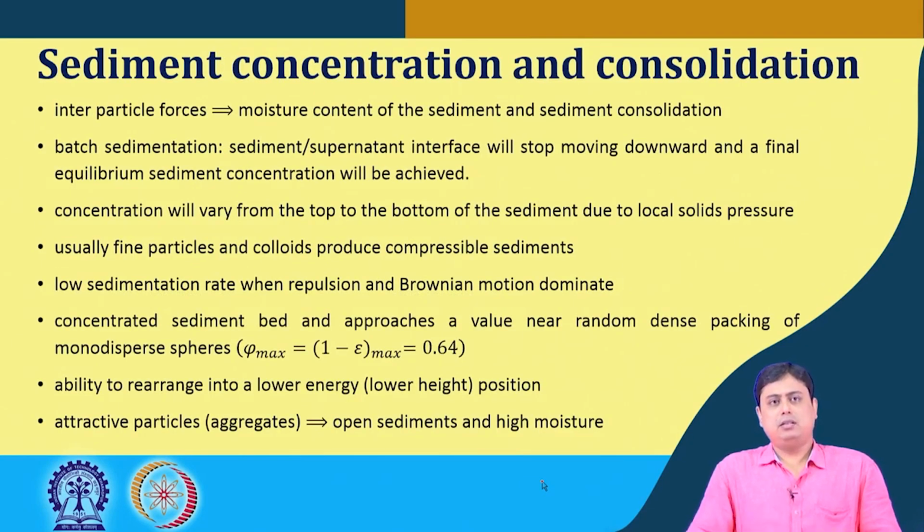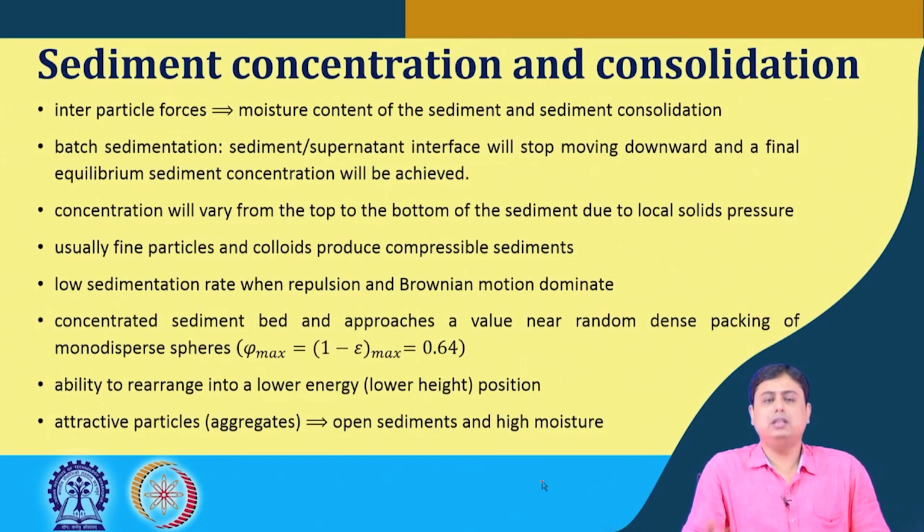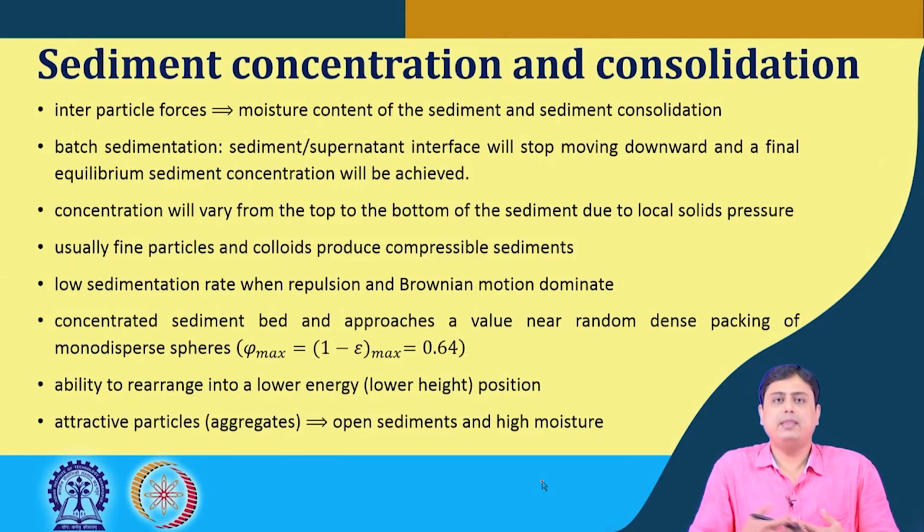So, that means interparticle forces dictate the moisture content of the sediment and the sediment consolidation. For example, in batch sedimentation, the sediment and the supernatant interface will stop moving after a certain time, and a final equilibrium sedimentation concentration will be achieved.